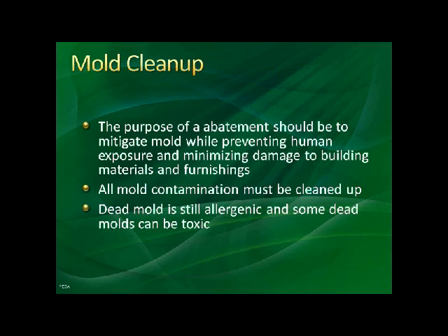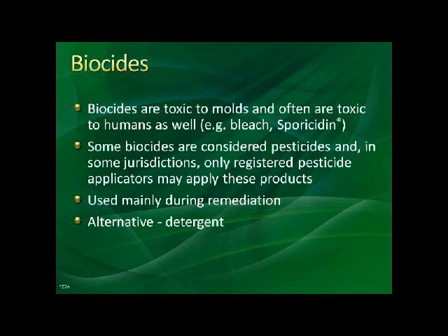The main purpose of remediation is to clean up the mold. It's got to be cleaned and returned to the nature that it should have been originally, which was clean and mold-free. All the mold contamination must be taken out. You need to understand, dead mold is just as bad as live. And I'm going to discuss this in a couple of slides from the IICRC S520, Guide to Mold Remediation and Abatement.